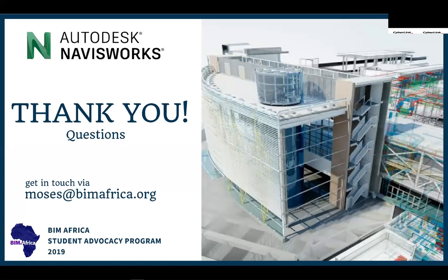So probably for trench excavation, you begin to say that you should note that as the length by the depth. For concrete, it needs to be set by volume. For reinforcement, it needs to be set by kilogram. So all of those need to be set. It is when you are setting those up that you select the components of the model that should be used for that equation.